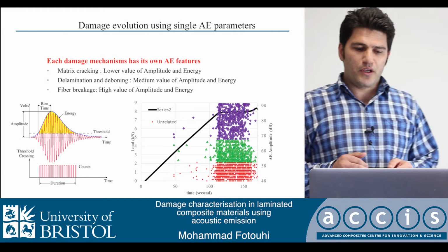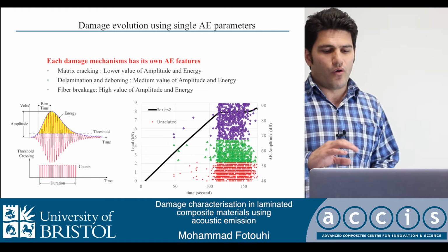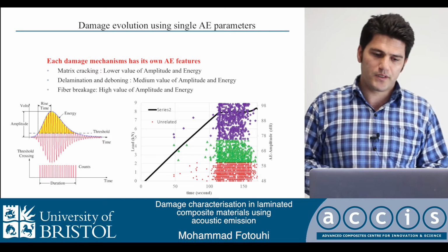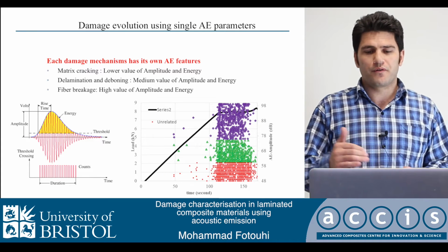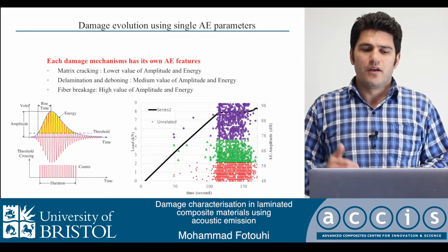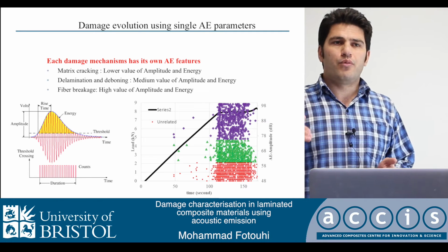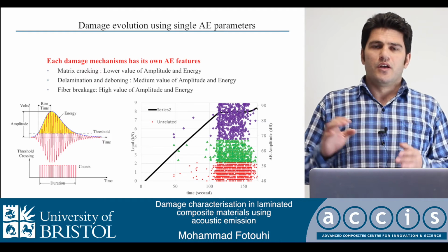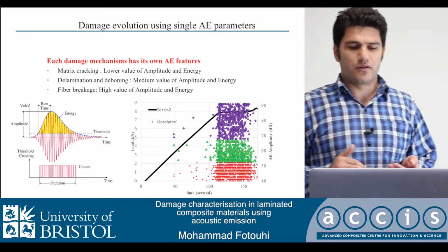A simple method that we used was separation of damage mechanisms using their own specific characteristics in the case of acoustic emission parameters. For example, we found that matrix cracking, which is one of the damage mechanisms, produces lower amplitude and energy, and delamination and debonding have medium values of amplitude and energy, whereas fiber breakage produces the maximum amplitude and energy in most laminated composite materials.